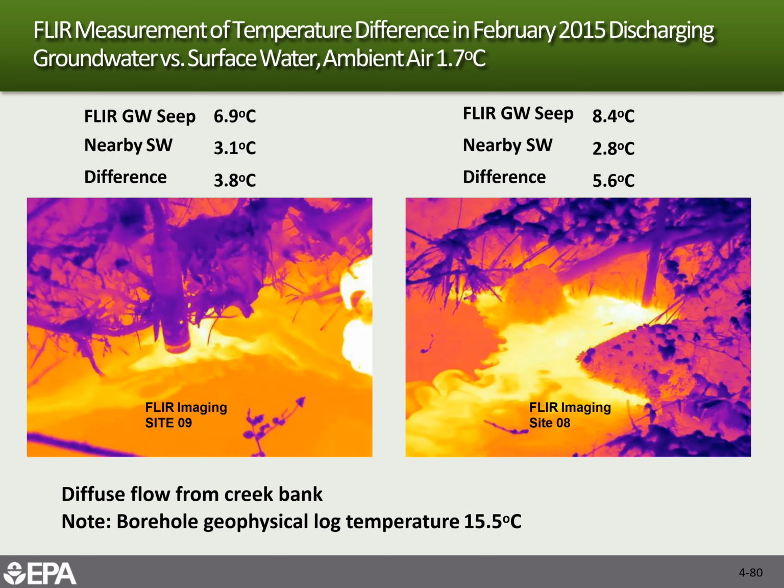This next slide is actually taken in the winter time, more of a diffuse flow, but again, you can really see where you should take your sample if you want to understand the concentration as the groundwater discharges and then mixes into the surface water, and then maybe take a sample 5 meters downstream to see what the average concentration might be after the mixing zone. But it really allows you to pinpoint specifically where the groundwater is discharging.